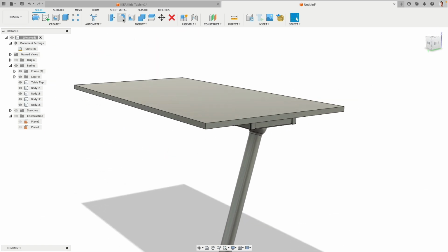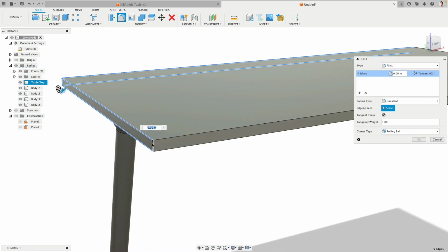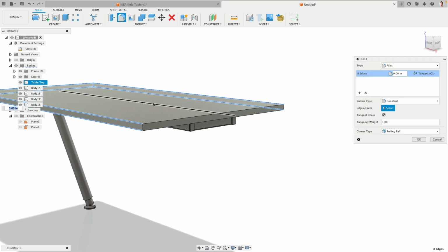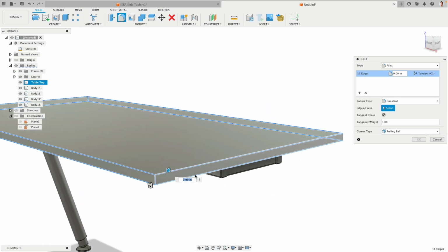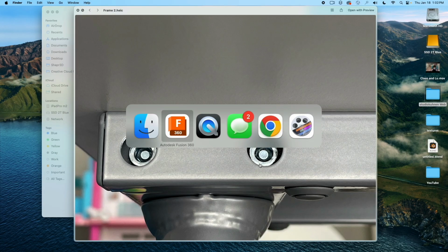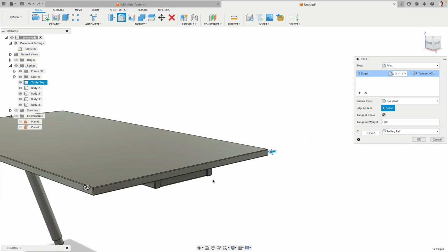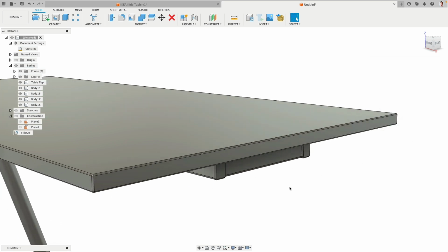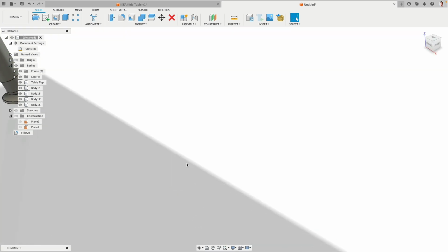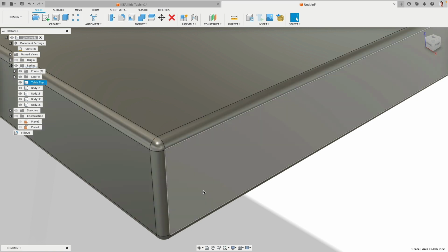And the tabletop needs to be rounded. So I will actually select all the edges of this tabletop at the same time. And you will see what will happen when we select all and then do a nice fillet, 0.125, and divide it by 2. That is actually very good. So when I zoom in now, you can see how we have this really nice triangular fillets and then all the others join onto it.